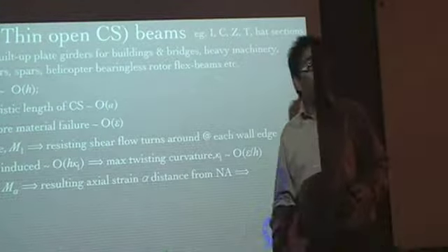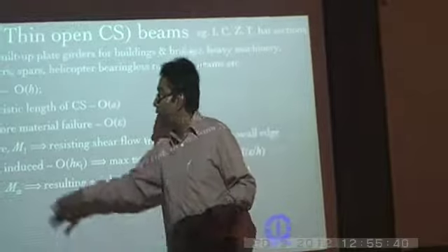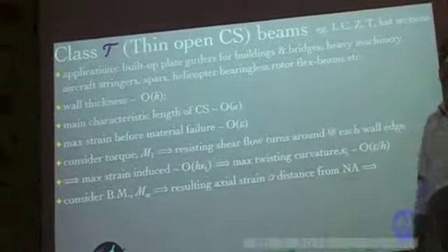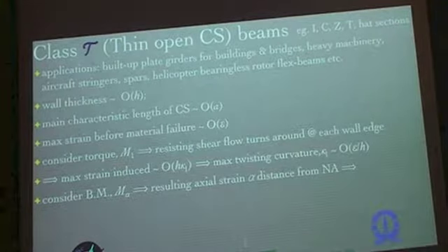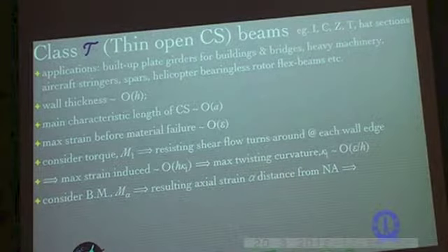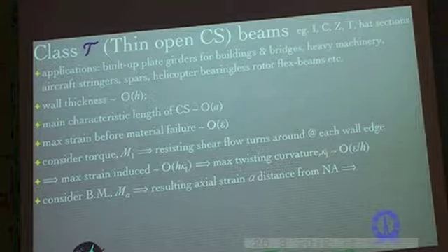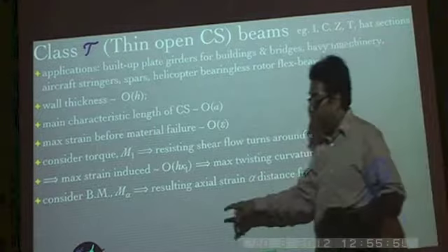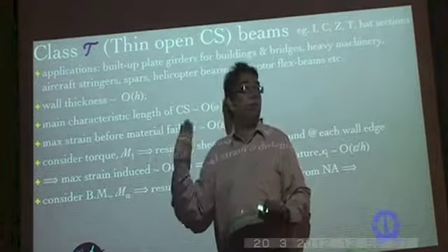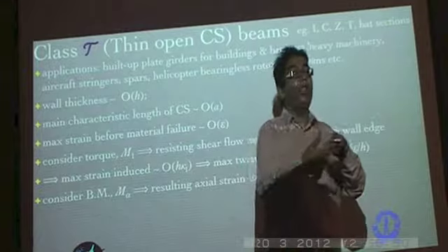Next example in the same case, for a thin-walled open cross-section, if you consider a bending moment M alpha, where alpha takes on the value 2 and 3. In the case of plates, we say alpha, or any Greek letter, takes on the value 1, 2, so don't get confused with that. Whereas in the case of beams, whenever we say any Greek subscript, unless we say otherwise, it takes on the value 2 and 3, which are associated with the cross-sectional directions.